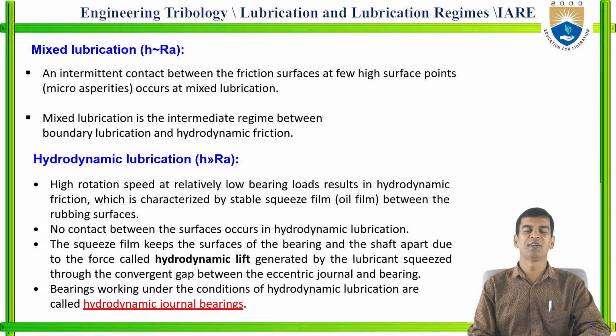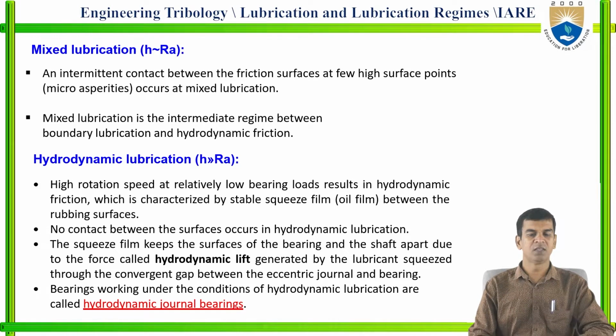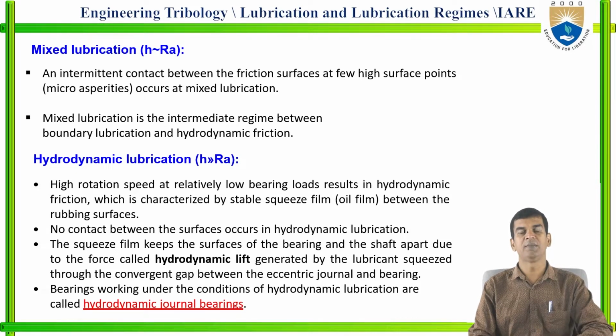The squeeze film keeps the surfaces of the bearing and the shaft apart due to a force called hydrodynamic lift, generated by the lubricant squeezed through the convergent gap between the eccentric journal and the bearing. In the hydrodynamic journal bearing, the surfaces are separated by the fluid.